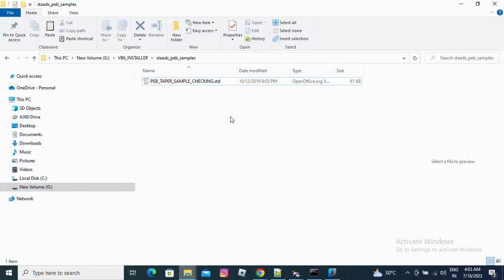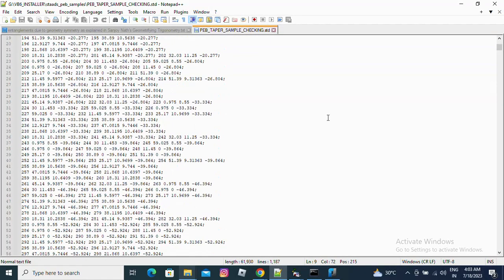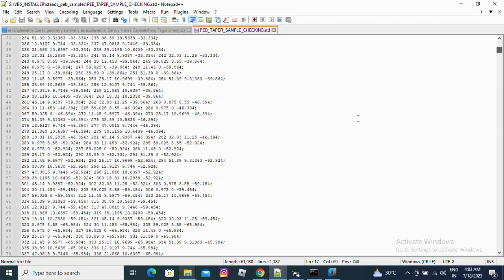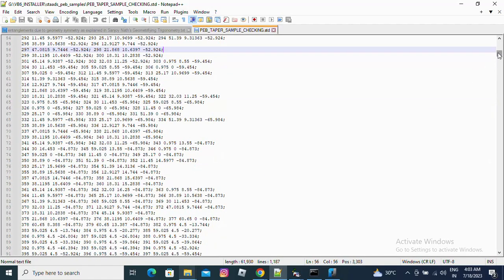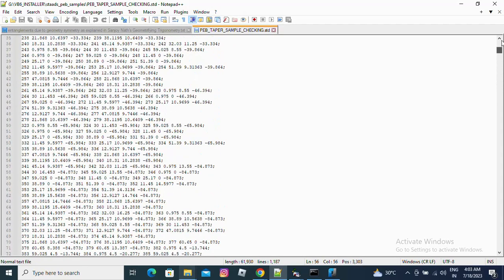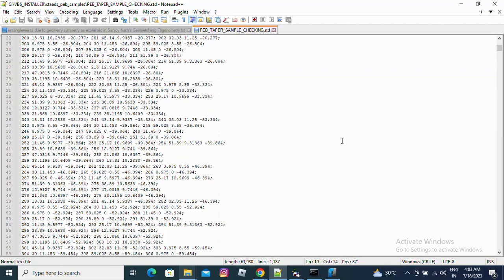Welcome. Today we will explain that in pre-engineered structures we get STAAD Pro files which look like this. This opens in Notepad. When engineers use STAAD Pro, they open these files geometrically and they can edit the command files like this. The structure of the STAAD files is very common, where people enter the data here and then they insert the joint coordinates.